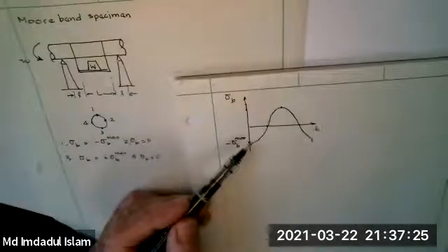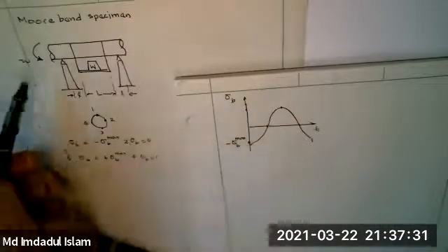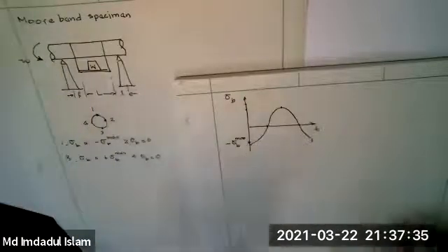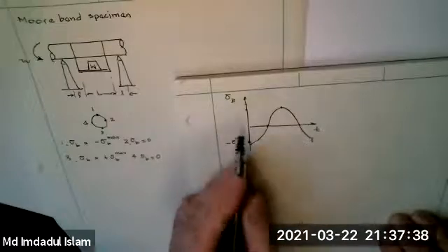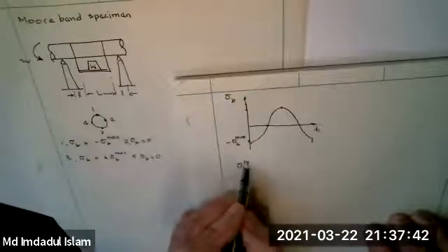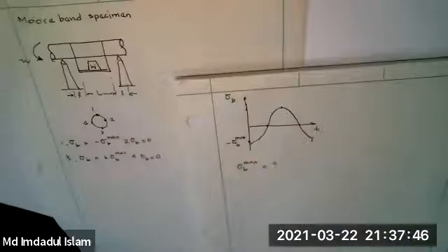These variations go 1 per revolution. You can have thousands of revolutions. So you've got far more cycles in bending than you do have in torsion. Okay. And so this is the dominant thing that breaks specimens. And so what we need to do to analyze this test more is we need to know what sigma B max is. Okay. Are there any questions on that?